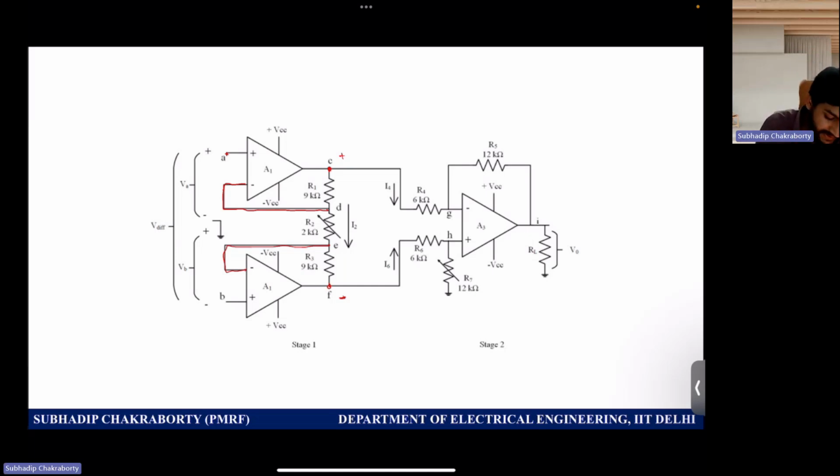Because you can assume like this, that whenever this value increases, then the output voltage is also increasing, and since the output voltage is increasing, this voltage is also increasing, and ultimately the steady state will happen where both voltages will be made equal, and hence virtual short will always be satisfied in such configurations.